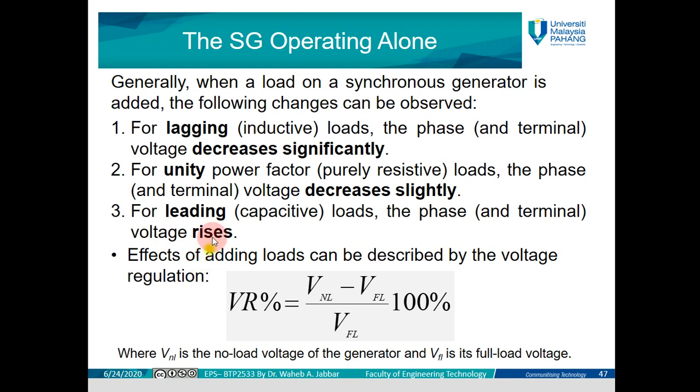Okay. So as we said before, we have reactive power, which is Q. So we have positive reactive power, Q, and negative reactive power, Q. The positive reactive power is generated from the lagging or inductive load. The negative is generated from the leading or the capacitive load. And usually, if we have inductive and capacitive load, it will be neutralized.